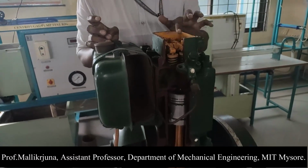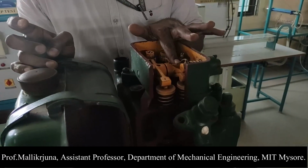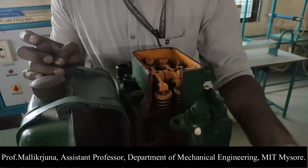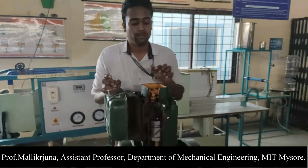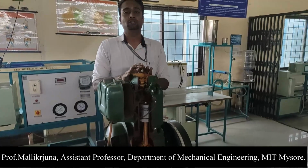That means I have one more reading now, that is nothing but closing of the exhaust valve. The exhaust valve is getting closed after TDC. I mean, after reaching the TDC, the piston is moving downwards. During that time, the exhaust valve is getting closed. So all four values I am available with now.